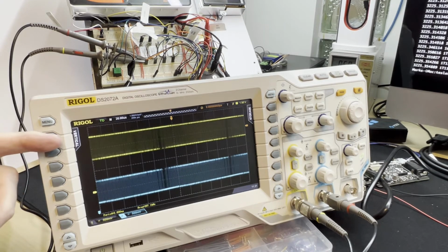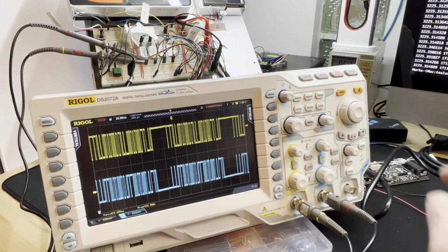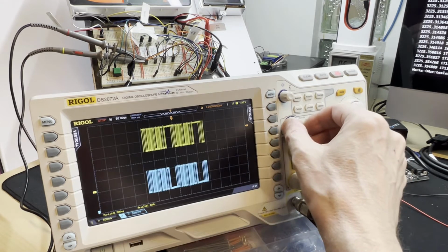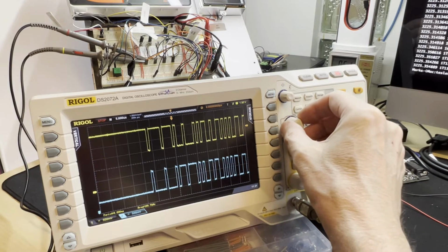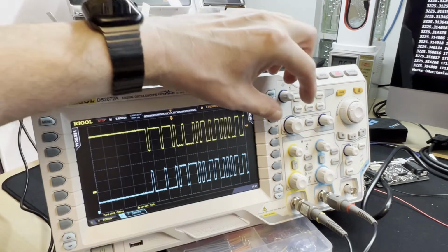The bus is running at 1 MHz, so that is 1 million cycles a second. Far too fast to see anything useful, so let's pause it with a single snapshot. Now we can see the data much clearer as the signal's binary 1s and 0s are represented by high and low voltage levels. This digital oscilloscope captures up to 2 billion samples a second, and this allows us to zoom in to get a much more detailed view.